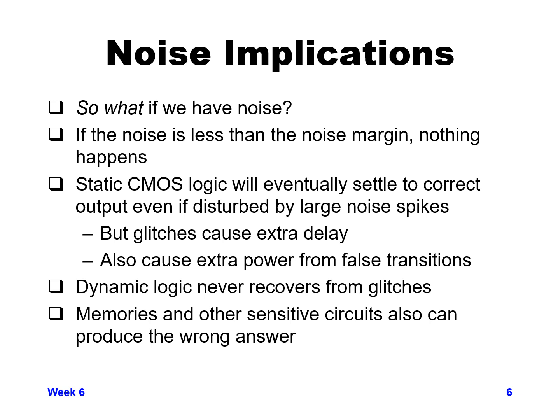A slightly less problematic thing is the glitching that you get from these false transitions could cause some extra power. Usually that's probably a second order effect that's not too concerning. But in static logic, that's probably the main problem: the glitch could happen at a time where, just at exactly the time when a downstream flop is trying to capture that data, as that glitch comes in, you get an incorrect value.